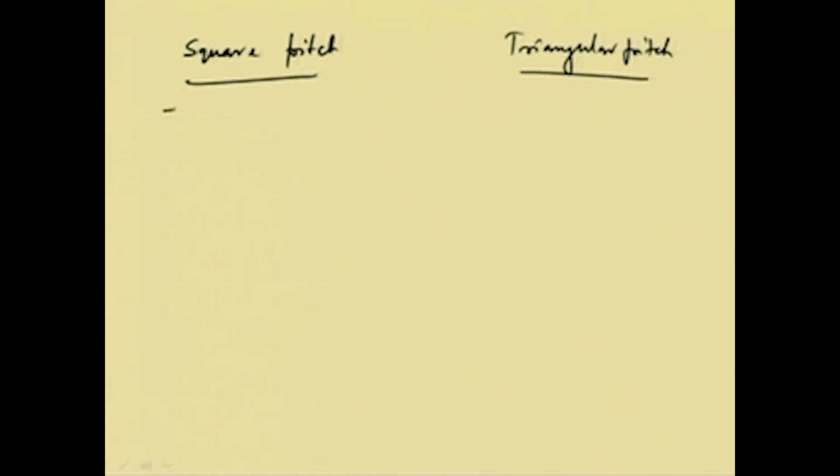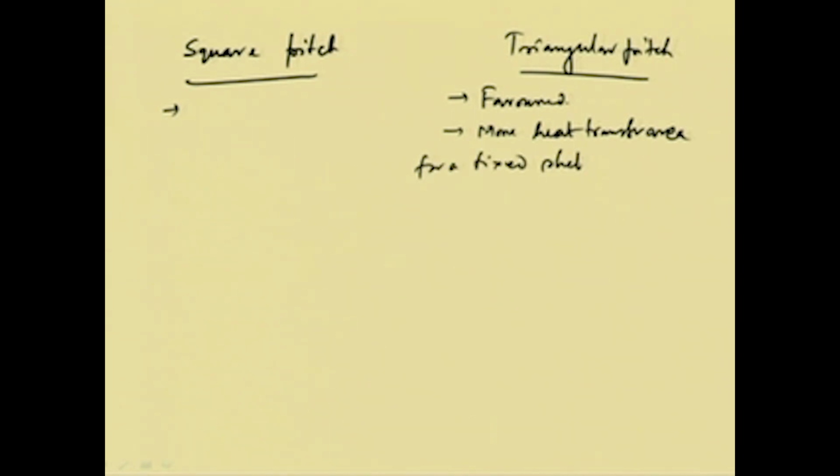In this case, triangular pitch is favored, because here we can say more heat transfer area for a fixed shell in comparison to square pitch.